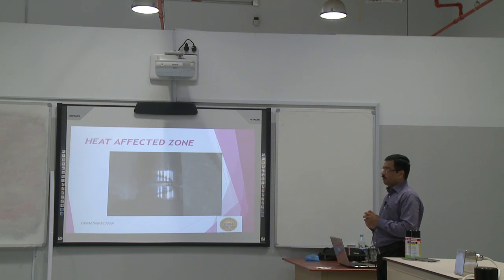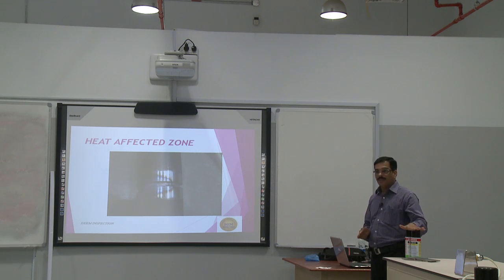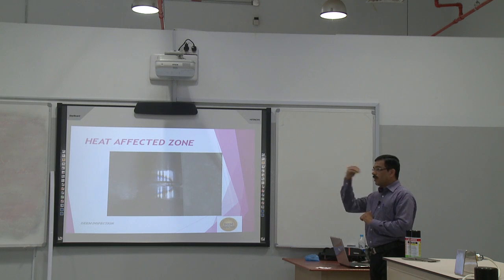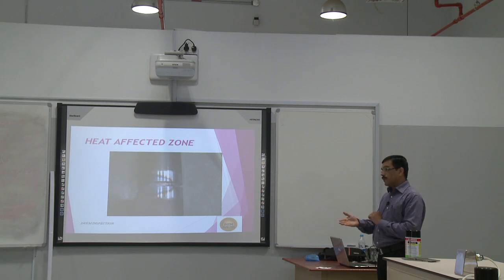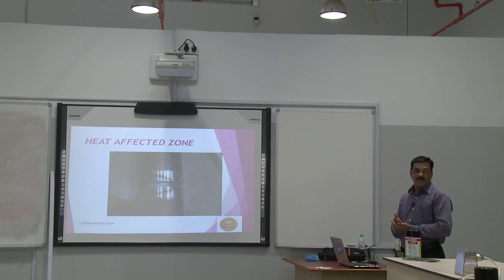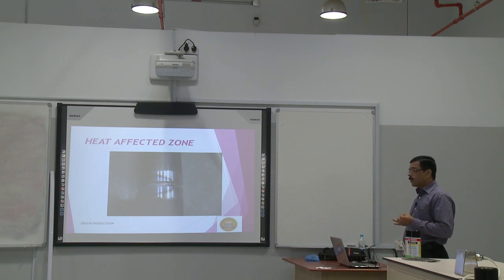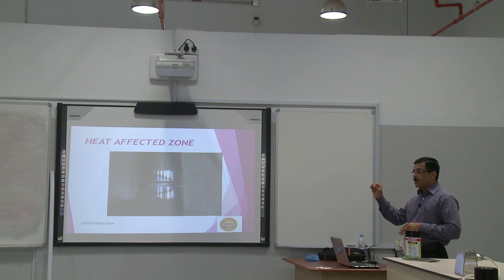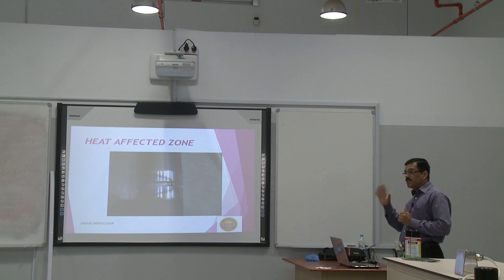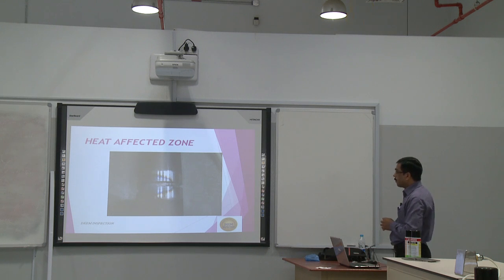What we are doing is we do the root pass and wait until cooling. After cooling, we apply penetrant testing. If it is okay, only then does the welder go for the further process. Otherwise, after 50 mm, 1 day, 2 days of welding, finally we will find that there is a minor problem in the root. We have to do a cutout. It is a loss of time, money, manpower, everything. So to solve that problem, penetrant testing is a very useful method. Anybody can do it. Not much technical skill is required. Anybody can do it at each and every stage of the welding to find out if there are any defects or not. So that's a good method.